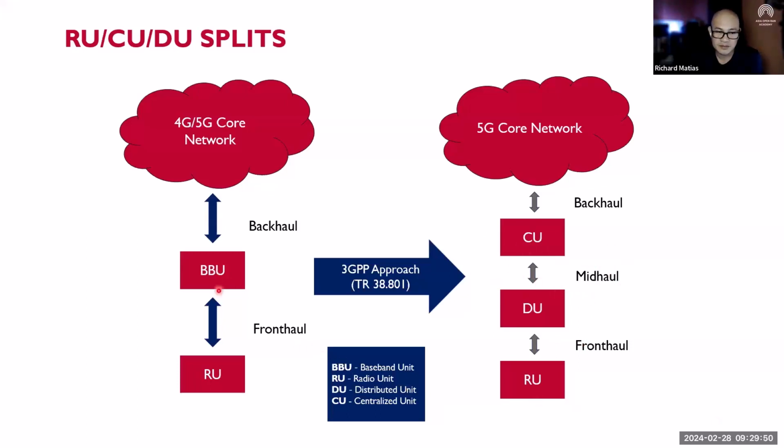Initially we have the fronthaul, the BBU going to the RU. This is the CPRI, and the backhaul is the microwave, fiber optic, or satellite. So that is still the backhaul. But since we are separating the BBU into two, we need a connection. We need an interface that we will call the midhaul. These are the new architecture introduced by 3GPP for Open RAN for 5G deployment.